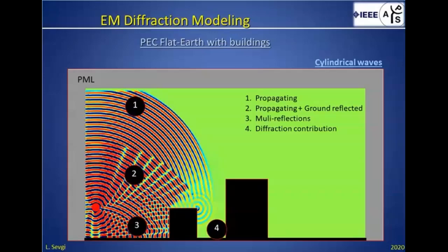In region 4, between two square objects, if you put your receiver in region 4, you cannot see the transmitter. So there is no reflection, direct wave, or refraction, but there is only diffraction in region 4, and also behind, on the right of the other objects.